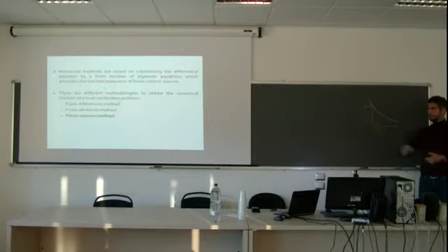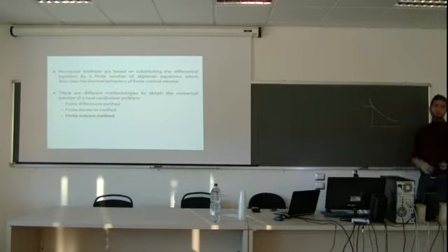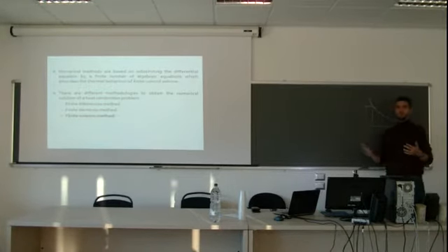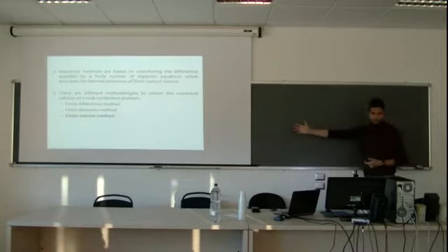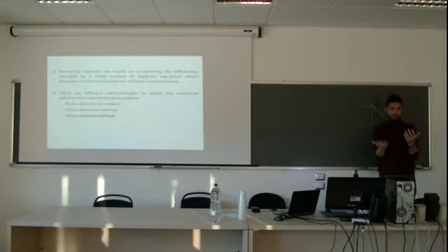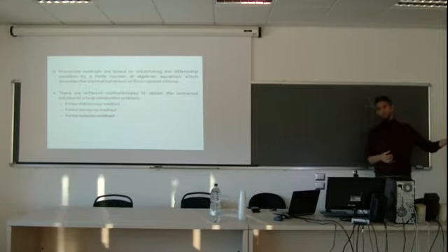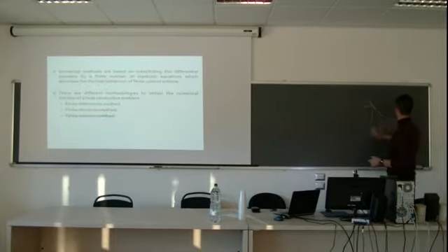I will say it later on, but sometimes adding more nodes is not a good solution because you can get convergence problems. But what this means is that if I want to simulate, I don't know, a car or whatever, I can divide the domain into different cells. The smaller the cells, the better results you will have, but the more computational effort you will have to carry out. Okay? Questions? No?